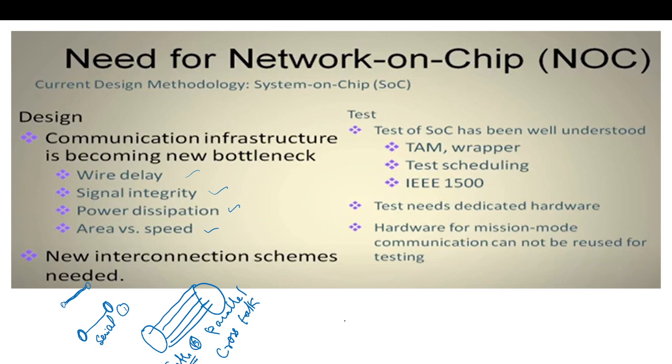Now, what does signal integrity mean? If we have two signals and say this line should always be 1, but because this line makes a transition from 1 to 0, and this line makes a transition from 1 to 0, if the lines are close to each other, instead of staying at 1, it goes to 0 for a short period of time. This is also known as glitches.